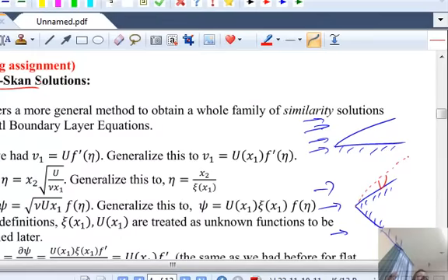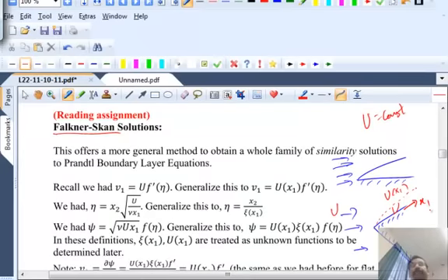The boundary layer equation is still the same, but now you will not have u equal to a constant. What is u? The u here is constant, but the u here is a function of x1. Okay, so there is a pressure distribution at the edge of the boundary layer. For the flat plate, that was 0.